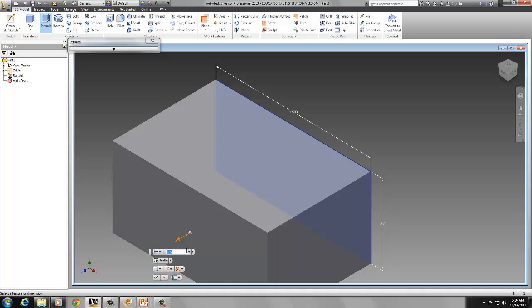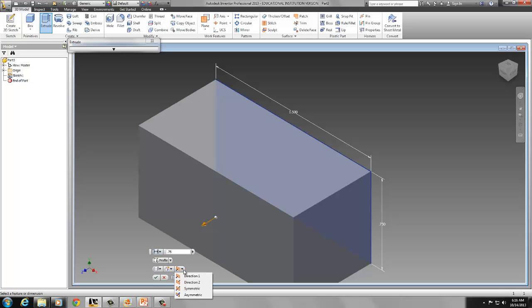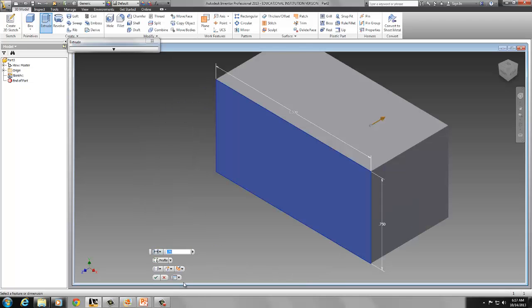For various reasons, I like to, first of all, it's got to be 3/4 of an inch. That's the size of our cube. I like to go inward, extrude inward. The default is outward. It turns out if you take my sim class and we start doing some milling, extruding inward helps. You'll notice that I can do everything I want here. So I can change the direction here.